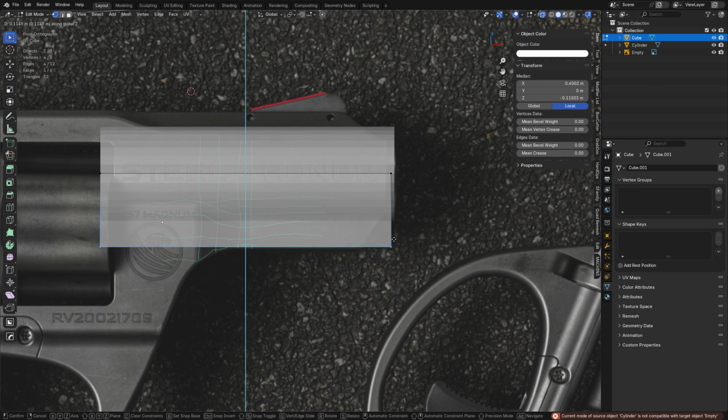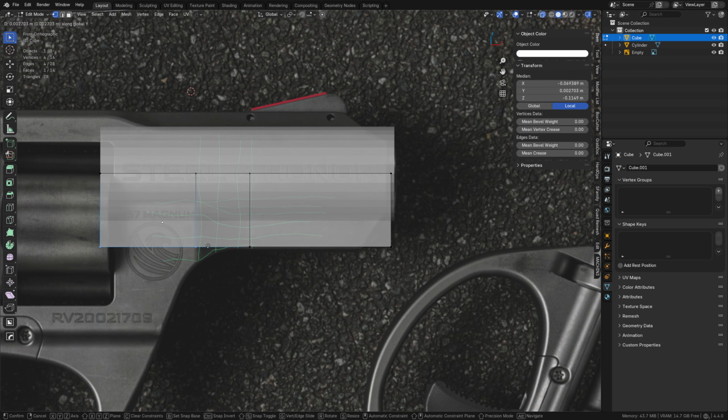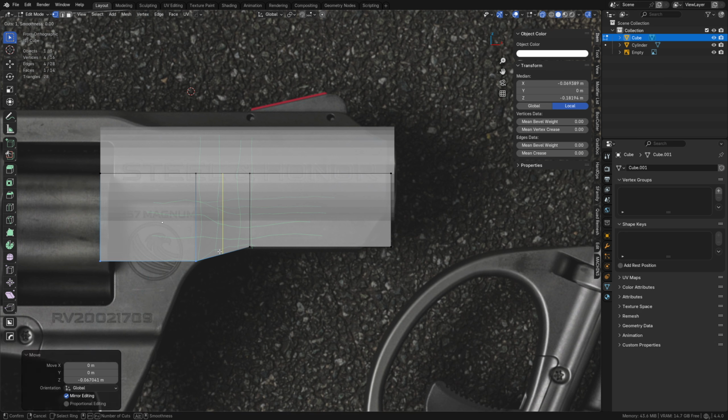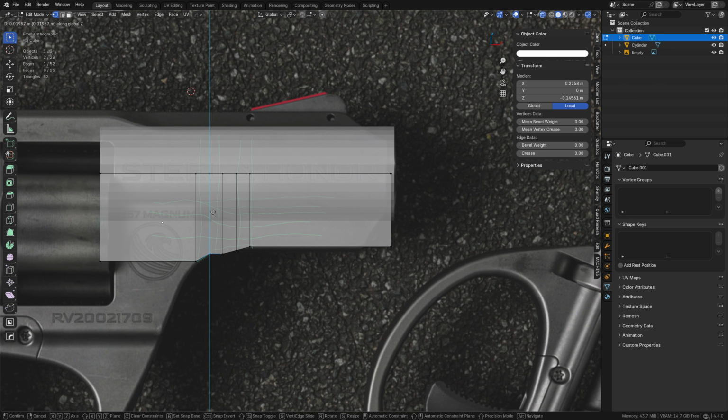Let's start working it out, basically. So if you're going to be doing subdivision, it's usually less faces. If you're going to be trying to do some kind of remesh workflow, you're probably going to create more faces or more bevel segments and things like that, right? Or you can do them non-destructively, of course.